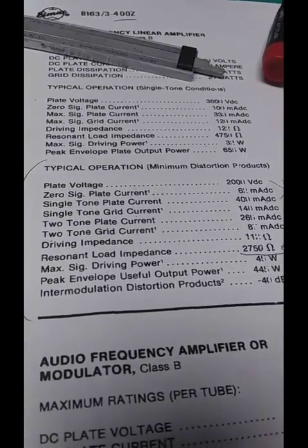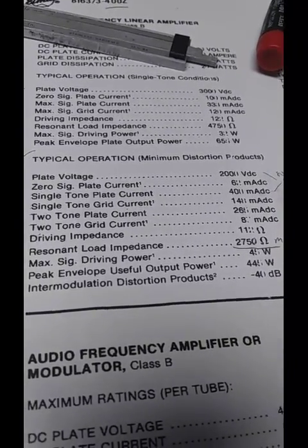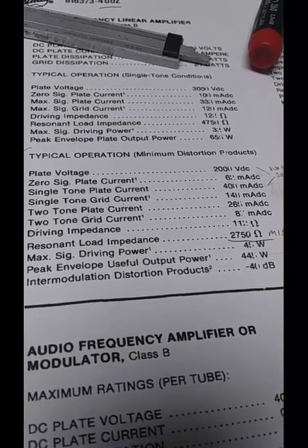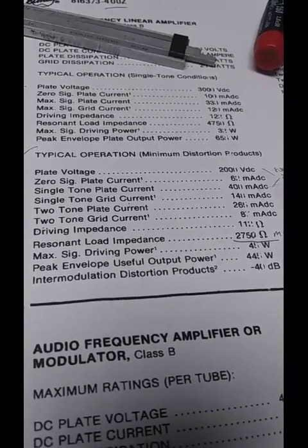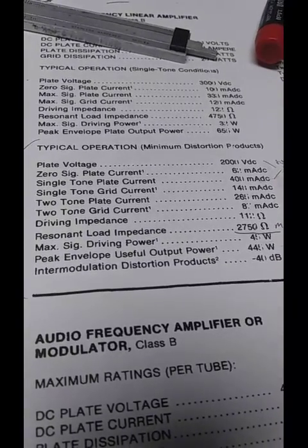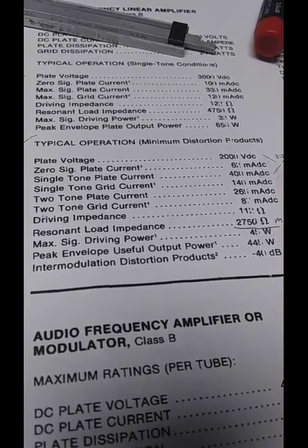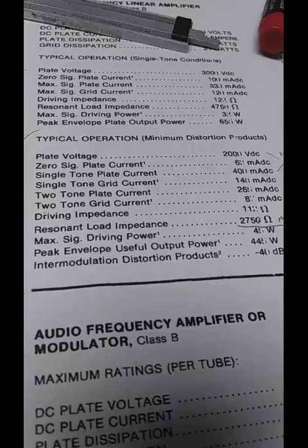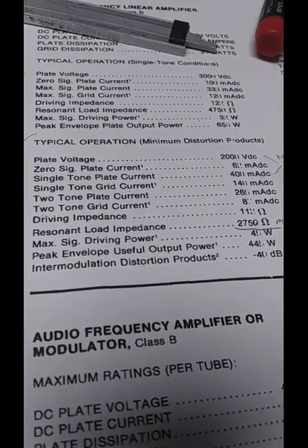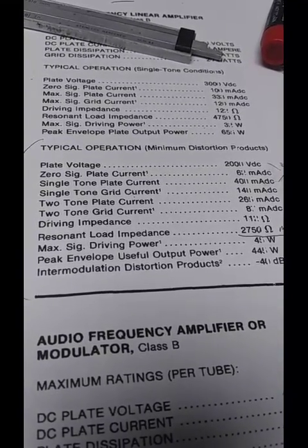So what I would do is vary the parameters here, and there's basically 2, plate voltage and grid drive, because that defines the transconductance, or the gain figure. And along with heater energy, which according to care and feeding accounts for 5 to 10 milliamp of plate current per watt of filament power. That's a very subtle and critical point. Never try to run an amplifier like this with an insufficient heater supply. It'll flat top.